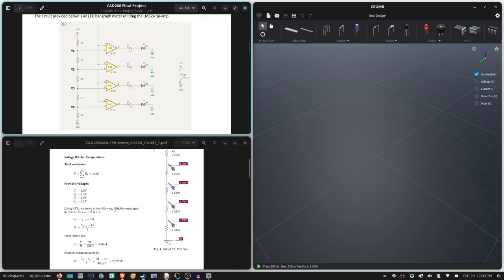And so we were given these voltages down here: 8 volts at V1, V2 would be 4.3, V3 over here would be 3 volts, and then V4 we wanted 1.1 volts. With the provided voltages, we aren't evenly dividing the voltage at each step, where we would have 9 at the top, 4 in the middle which are divided evenly, and 0 at the ground level.